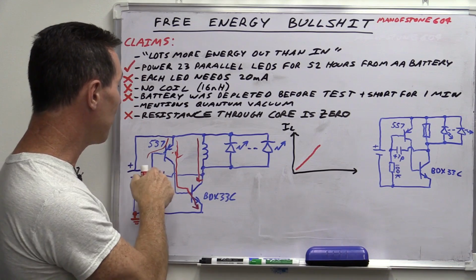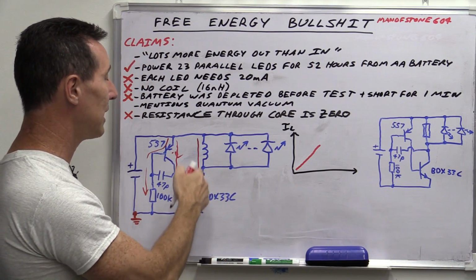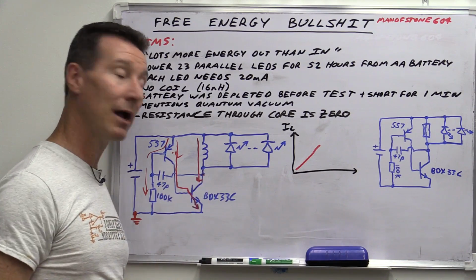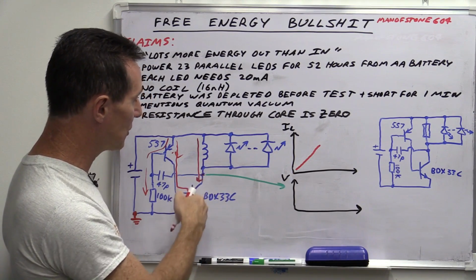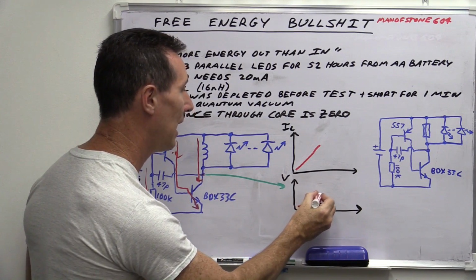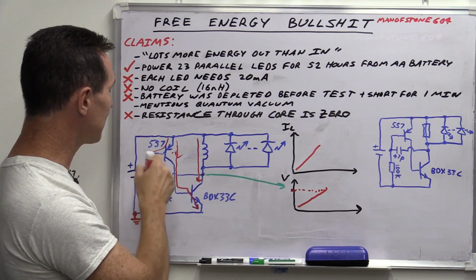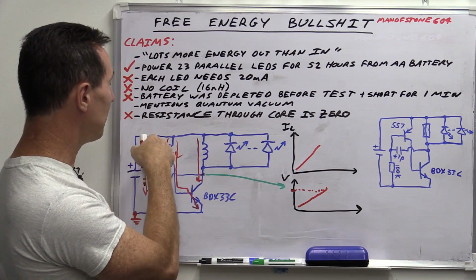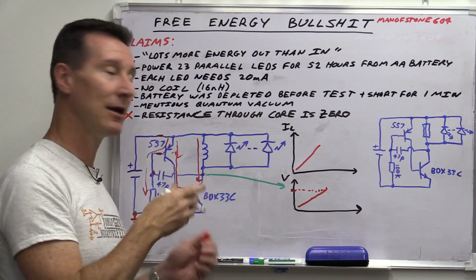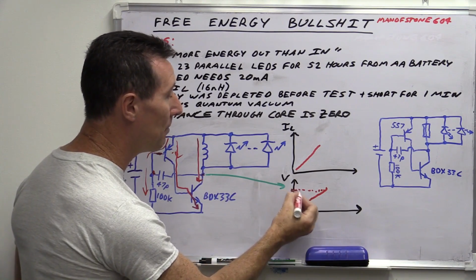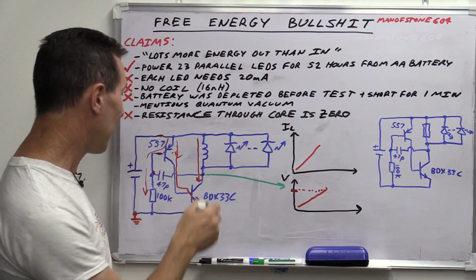It's only 47 pF, but remember that one's going to start charging up as well. And this voltage here, of course, is going to start going up as well, because as you increase the current, you're going to get a bigger voltage drop across your transistor here. So we'll draw that waveform as well. This is this point here. As the current rises through this inductor and hence through the transistor, the voltage drop across the transistor is going to rise as well until it hits a point somewhere here whereby virtue of this feedback capacitor, the voltage on the base of this transistor over here is below the threshold voltage of the base emitter junction, i.e., your 0.7 volts or whatever it is. So it's going to rise up to about 0.7 volts below the battery voltage here, i.e., it might be 0.5 volts or something like that. So it rises up to that point.